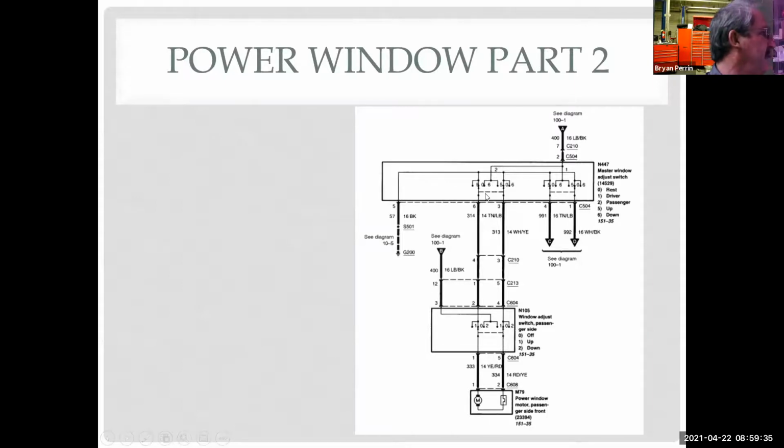And if you notice how the switch moves, these are joined. So when this moves this way, it's touching ground here and power here. If it moves this way, it's touching power here and ground here. So you see how that works, right? So am I touching these? Am I touching these? That is what it's doing. Kind of ingenious, actually. And I'm reversing direction. So my two center ones are power. My two outer ones are ground. So I'm changing direction on the switch.